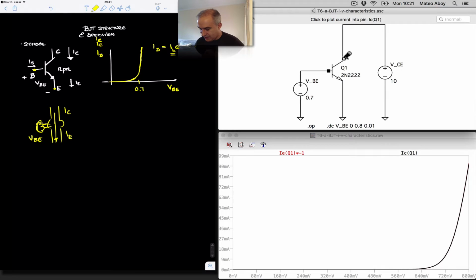Now, we can think about this device as, therefore, as a transconductance device, meaning we are creating a voltage control current source. And voltage control current sources are of course useful to create current sources, but once you have current sources, you can also create amplifiers.